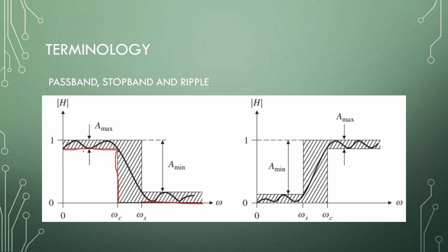This is all based off a brick wall kind of filter, so the perfect filter would be a perfect passband and then just stop. As you can see, there is a ripple defined in the passband and in the stopband.